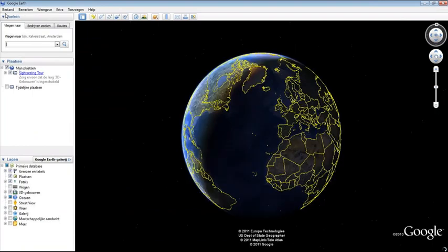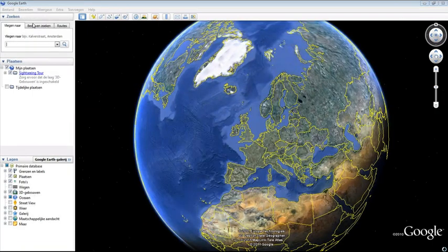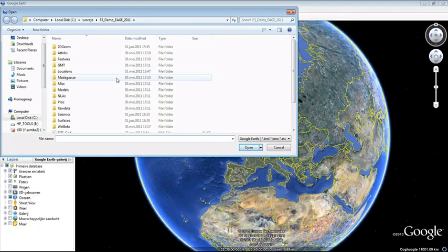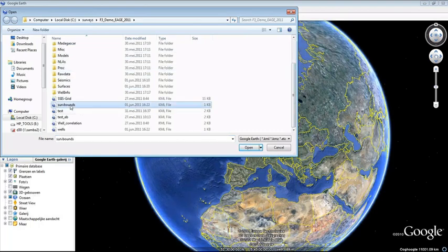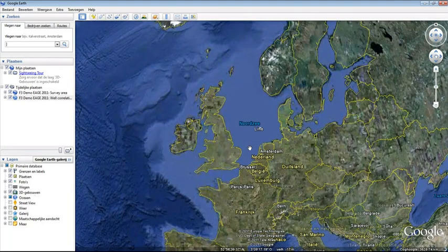So I will just open the file I've created. Open. In the same location, survey. Let me find my KML. It should be here already. Survey bound. And for instance, this well correlation. Click OK, and the Google Earth will just show me the location of my survey.